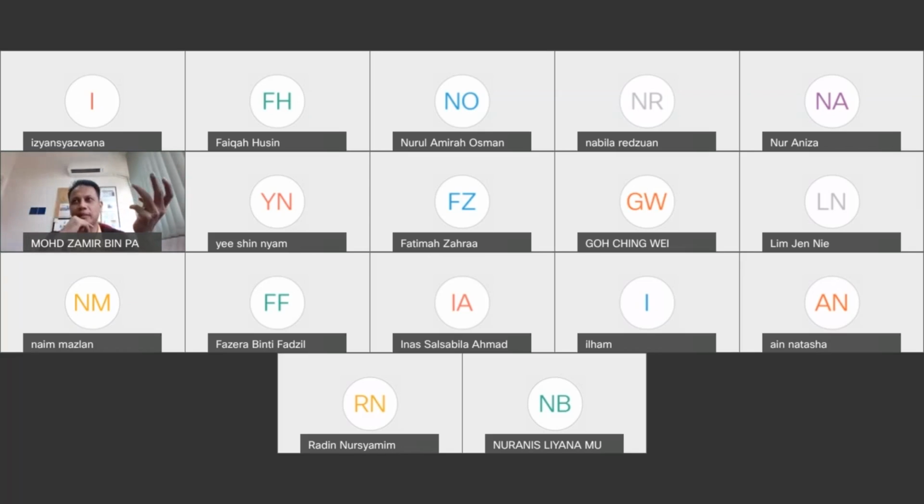So we've discussed yesterday about DT product, diffusivity times process time. So you have diffusivity of phosphorus, diffusivity of boron, and whatnot. And if you induce high temperature, diffusivity is dependent on the temperature as well. So if you have subsequent high temperature processing in processes that are not diffusion, but you run high temperature, those high temperature processing could actually cause dopant redistribution from your diffusion process.